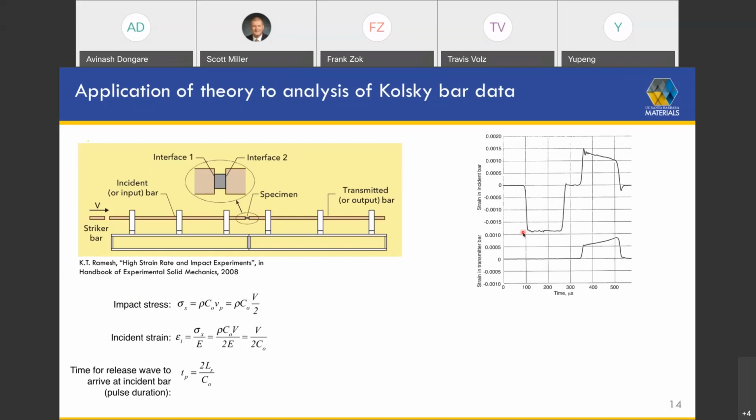And so what you find as a result, when you get into this very ultra high strain rate domain, is that the flow stress, or the stress versus strain rate plot, starts to plateau. And that again is true of virtually all materials.